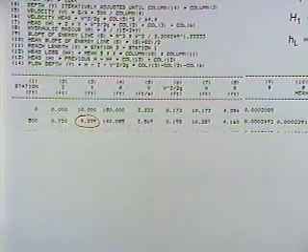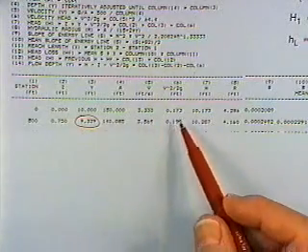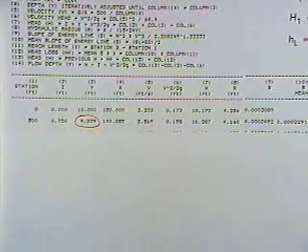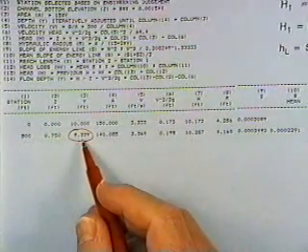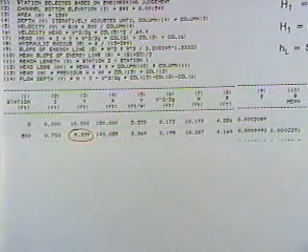And then I know that if I take the head at this location, that's the total head, elevation head plus pressure head plus velocity head, and subtract from it the velocity head in this column minus the elevation head in this column, the only thing left is the depth. So if that depth comes out to be this initially assumed depth, I'm home free. But in general it doesn't.